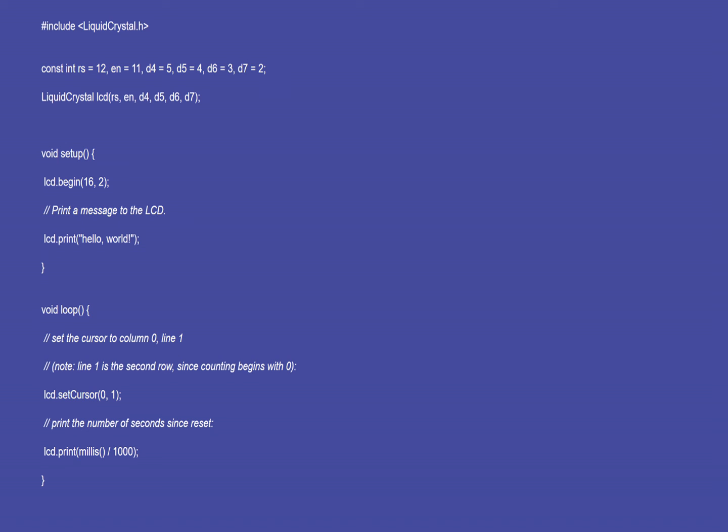Also, the cursor function is used to display an underscore cursor, and the noCursor function is to turn it off. Using the clear function, we can clear the LCD screen. The above code is simply there to educate you about the liquid crystal library and its various functions. Hopefully, you understood what it all meant and are ready to write your own code.